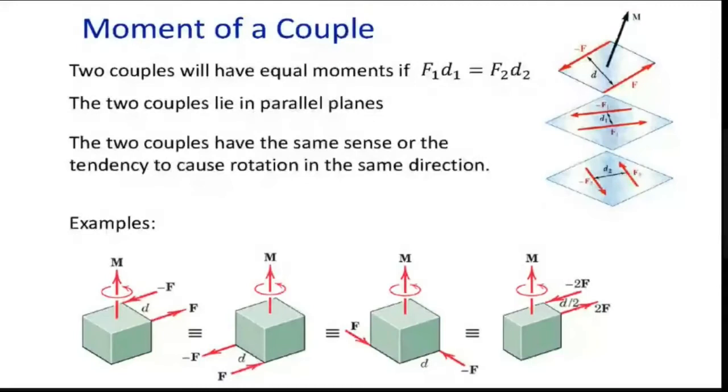No, sir. So moment of a couple. A couple is a pair of forces, actually, which have the same magnitude but act in opposite directions. And they should be parallel forces. If you have two parallel forces, the magnitude is the same. If one side is F, the other side is also F, and the direction is opposite. It forms a couple.